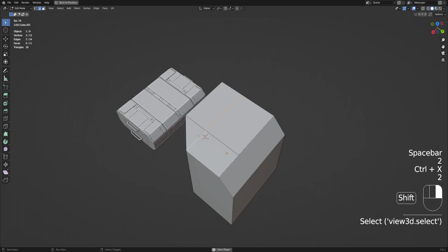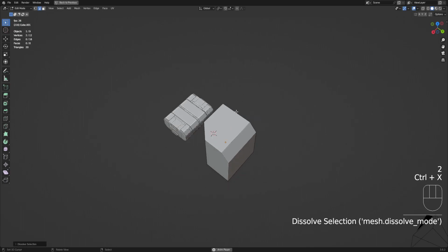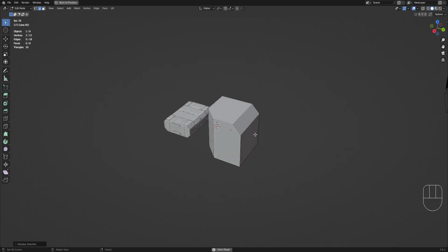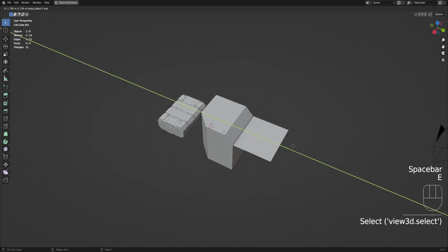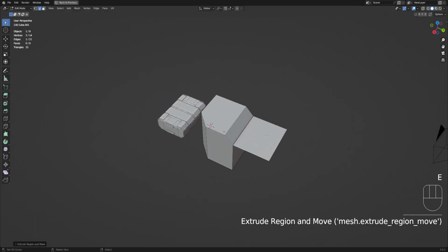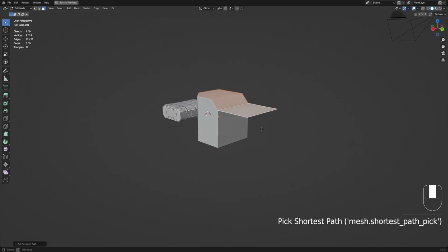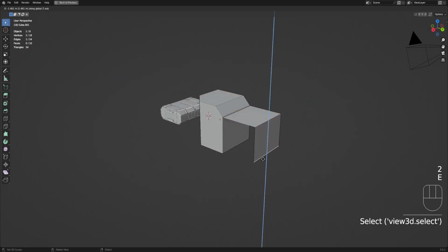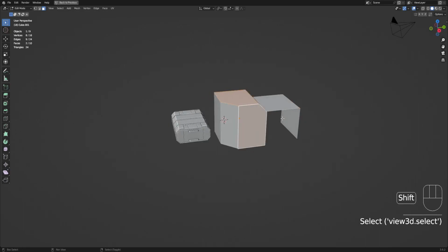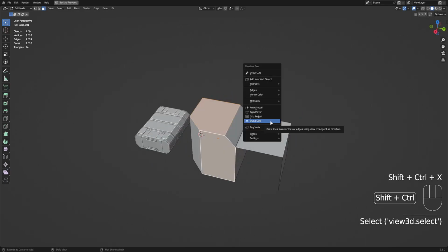So when you're selecting faces for Quad Slice, all the selection must be on the same normal plane, like this. It could sometimes work with this selection, but just to avoid any errors, like from this selection here.